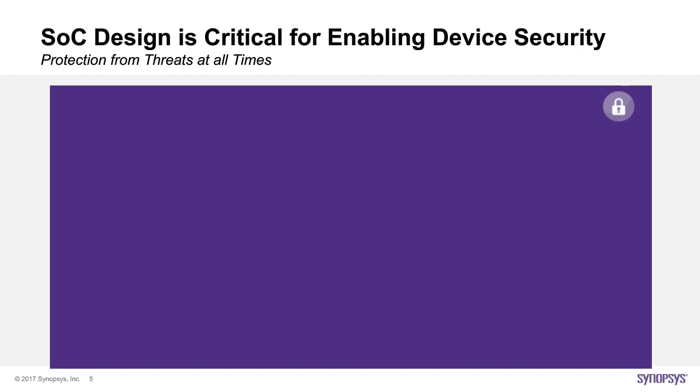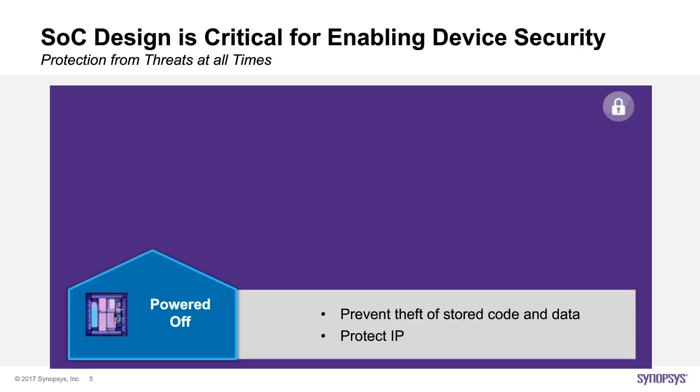The image and data is at rest and in persistent storage, for example, like a flash device. Is it required for the image and/or data to be confidential? If so, you'll need some form of encryption and decryption. Do you require a form of tamper protection if someone changes the information? Well, then consider a form of authentication. Can you ensure the information cannot be shared across different devices? Well, then you'll need a way to uniquely bind that data to that device.